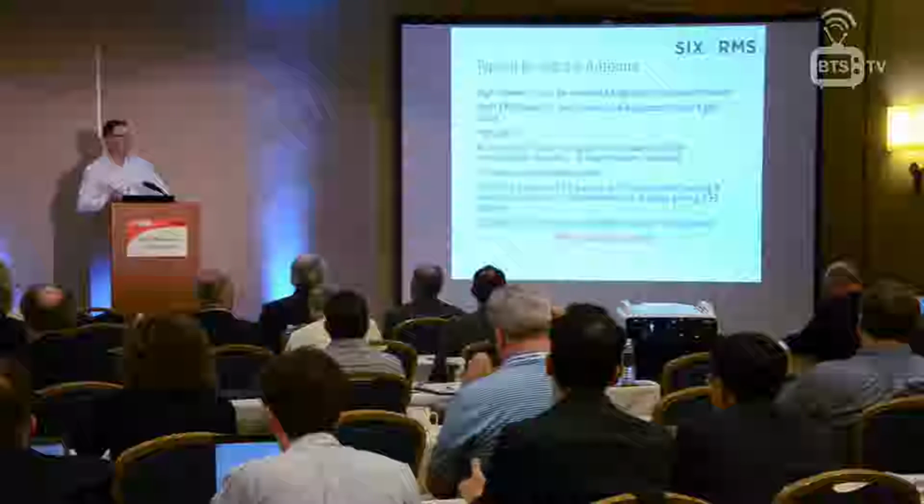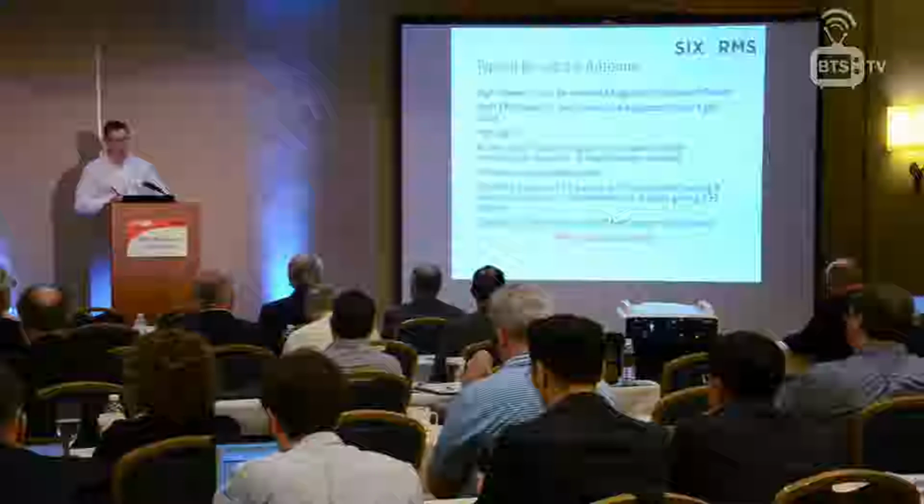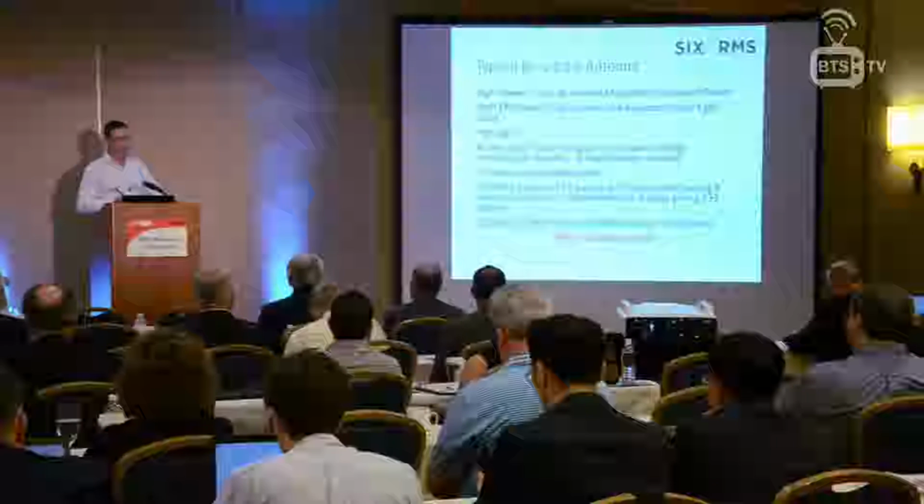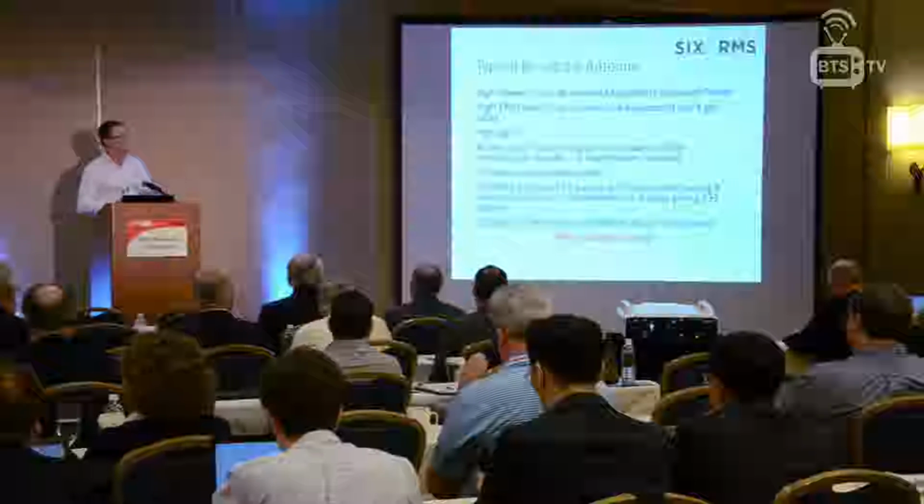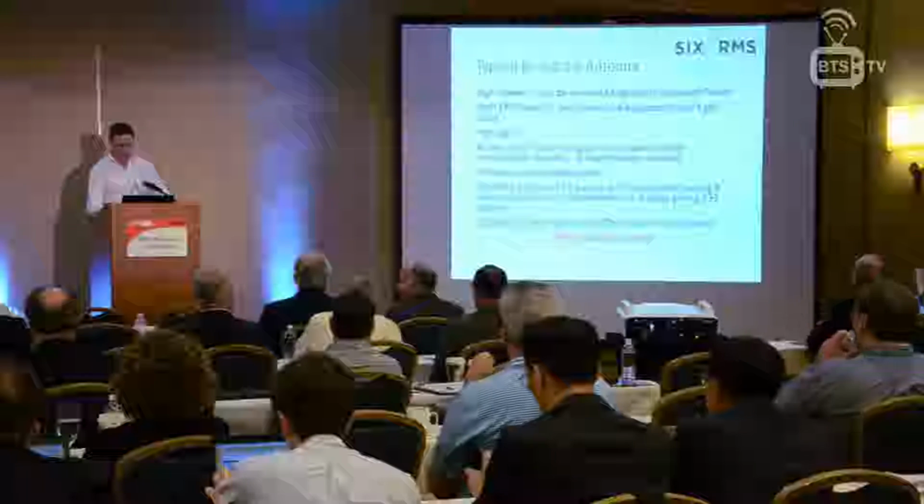Typically there might be 4 faces of 12 panels, and each panel would have 4 horizontal dipoles for a horizontal TV service. So that's 48 elements on 4 faces, 192 dipoles. Typically they'd be 50-foot long antennas, maybe 600 feet above the ground. What could go wrong really is the question we could be asking ourselves.